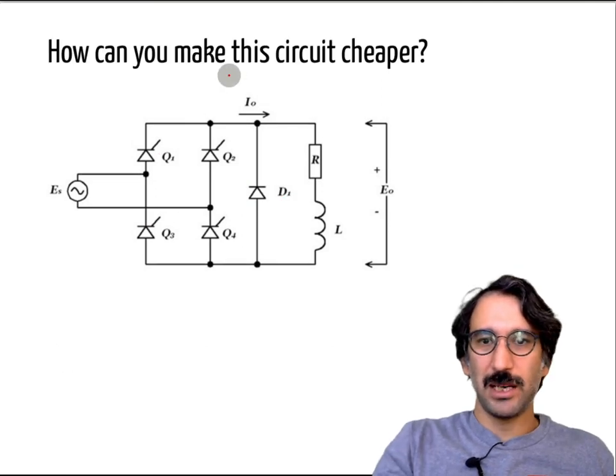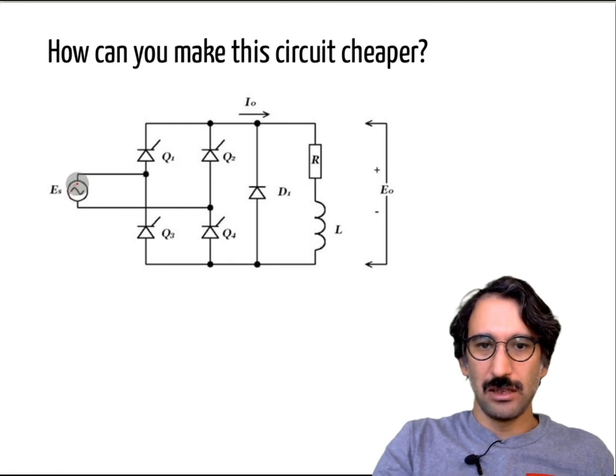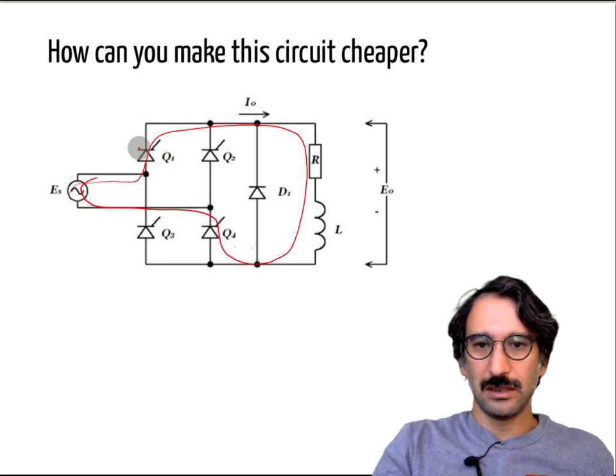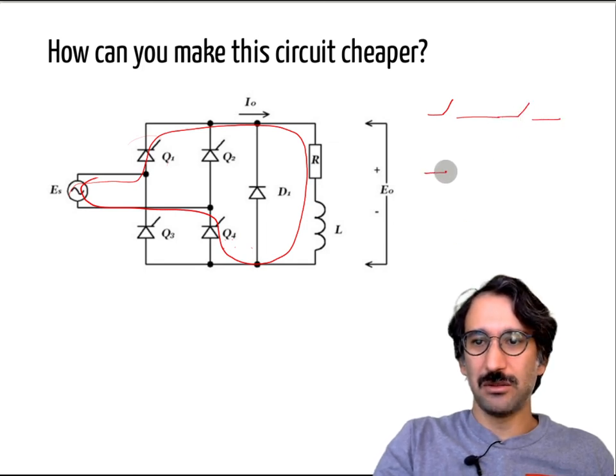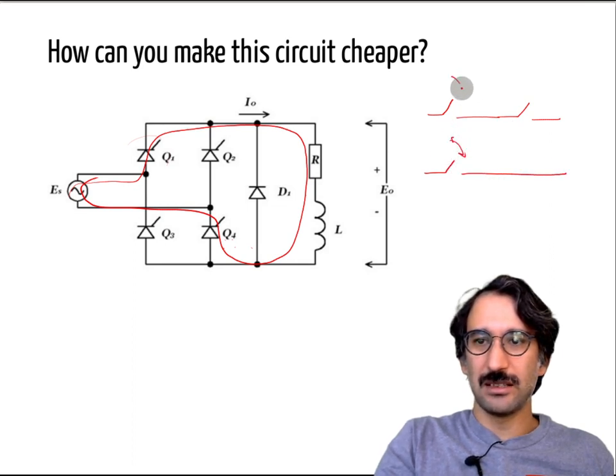So how can we make this circuit cheaper? If you think about it, whenever the current flows, I have 2 thyristors in series, like 2 switches that you can control in series, right? I can do the same logic by putting a single switch, and the other one can be a slave, instead of having two masters.